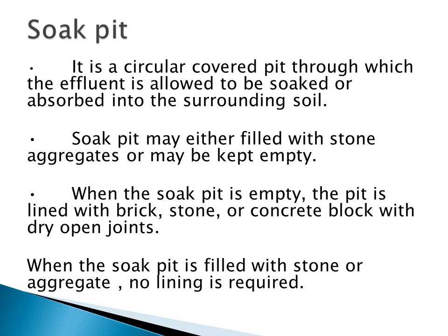Here the soak pit is nothing but a circular covered pit through which the effluent is allowed to be soaked or absorbed into the surrounding soil. Normally it can be filled with stone aggregate, or it can be kept empty also. When the soak pit is kept empty, the pit is lined with brick, stone or concrete block with dry open joints. If the soak pit is filled with stone aggregate, then no lining is required for this soak pit.